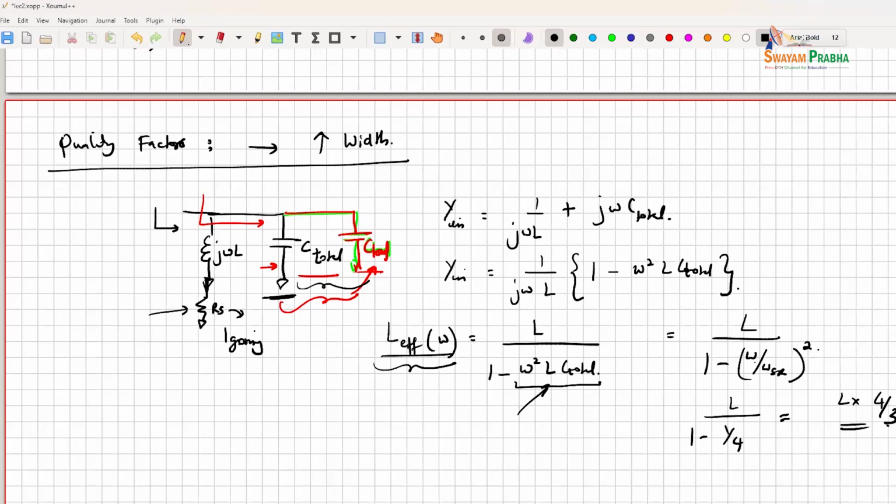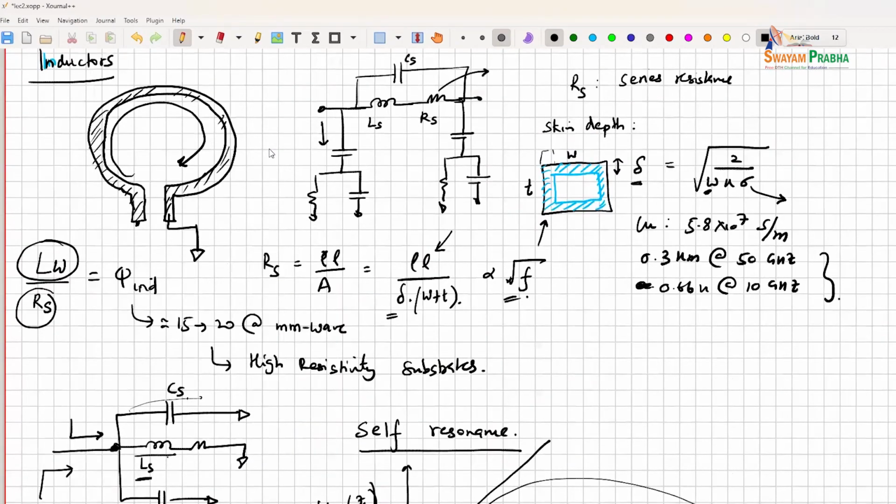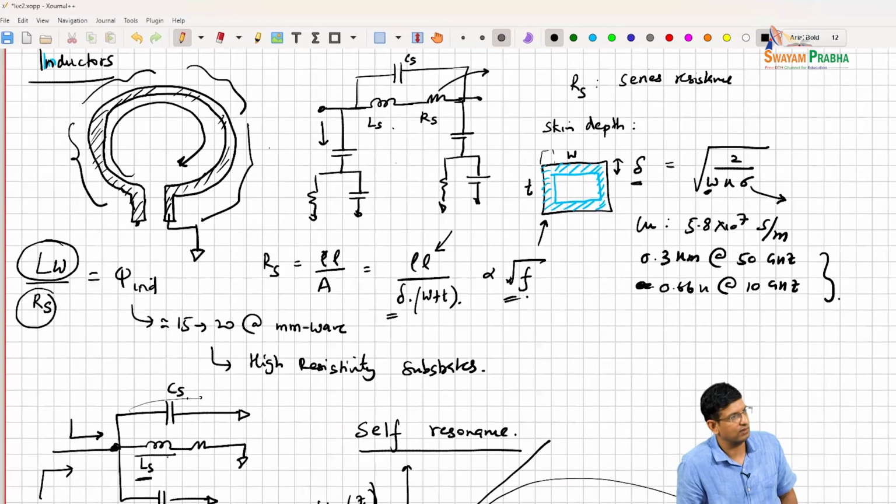Now, having said this, the only other caveat that I would say is that this model itself, as we discussed when talking about lumped and distributed circuits, is not a wideband model. So if I want to truly make a wideband model for this inductor, I maybe divide this inductor into 4 sections, and for each section I have this model.